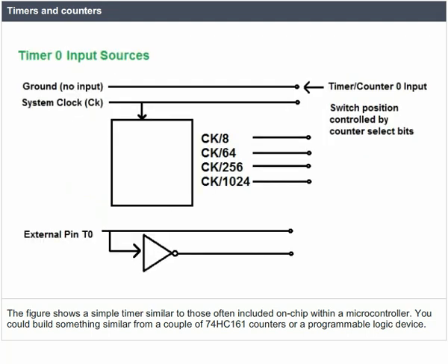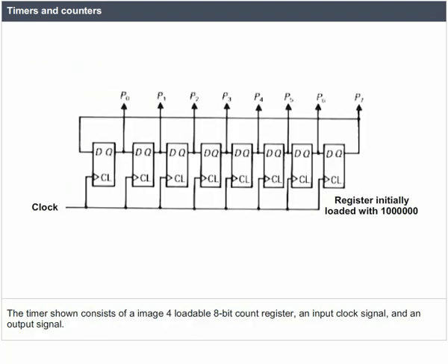Timers and counters. The figure shows a simple timer similar to those often included on chip within a microcontroller. You could build something similar from a couple of 74HC161 counters or a programmable logic device. The timer shown consists of a loadable 8-bit count register, an input clock signal, and an output signal.